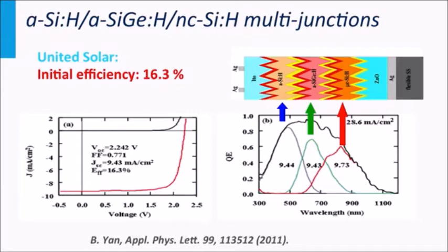Wavelengths at 550 nanometers are utilized by the top cell and middle cell. Wavelengths at 650 nanometers are utilized by all 3 junctions. Wavelengths above 900 nanometers are only utilized by the bottom cell. Consequently, optimizing thin film silicon multi-junction solar cells is a complex interplay between the various thicknesses and light trapping concepts used in the solar cell.